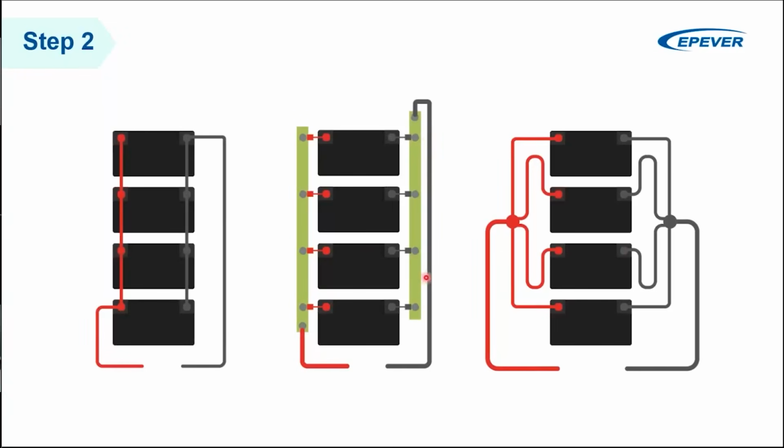These are the bus bars. You can use the bus bars for that, and you can use these kind of cables. And why are these twisted? Because it has been taken into account that the length of this cable should be equal to the length of this cable, so that the resistance towards all the cables is equal. So this was the point that I felt is worth mentioning here when we are designing the system.